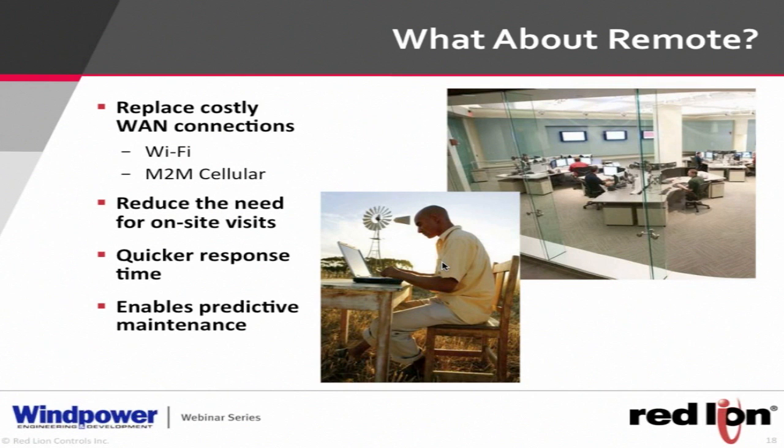In the past, people had connections with a T1 line or ISDN or something like that, and those lines end up costing a pretty good bit of money. But now with cellular and Wi-Fi communication, Wi-Fi costs you nothing as a monthly fee. You pay for the radio itself at the very beginning, and then the Wi-Fi communication is unlicensed, so you use what you need to. With cellular, you pay for a machine-to-machine cellular connection, and you pay a very low amount for the amount of data that you're actually pulling down. In a cost comparison, cellular is much better than a T1 connection would ever be.